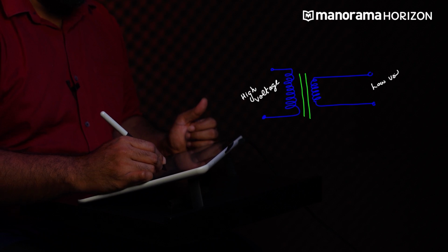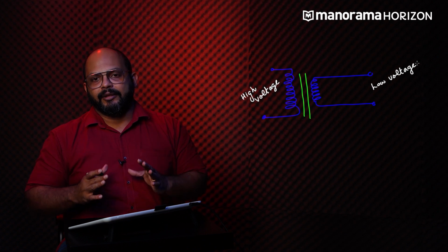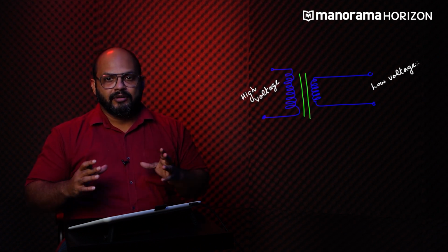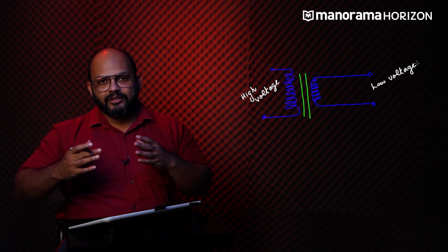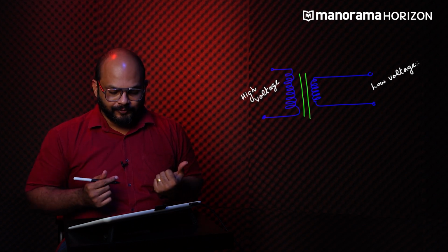That is why we call it a step down transformer, because it reduces the voltage of the incoming AC signal. Please remember, a transformer does not change the power level of the signal. So if you are reducing the voltage on the output side, you're also stepping up the current in equal proportion.